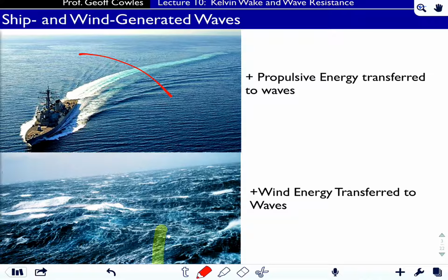So we keep the same Froude number and have a geometrically similar wave train, measure the wave drag coefficient on the model, estimate friction drag using a formula, and that'll allow us to scale up the total drag. We'll see the process in more detail after the break, up to the full-scale model.